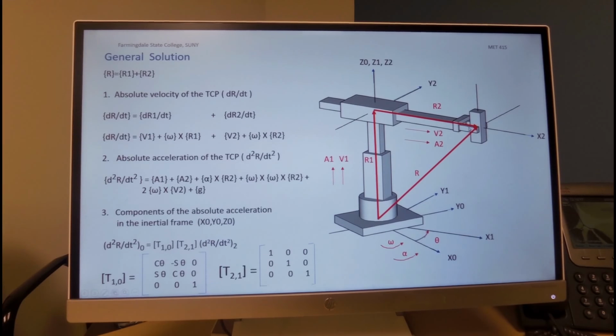So there will be a direction from omega rotated in the direction of r2, following the right-hand screw rule, in the direction of y2. So the tangential velocity will be in this direction of y2, and this is called the radial velocity, v2, along the radius.